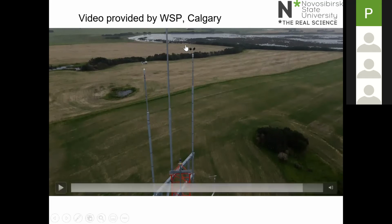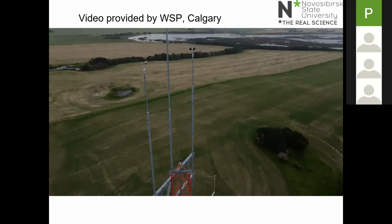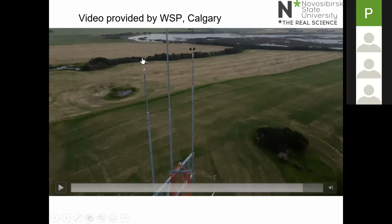These are very simple cup anemometers. You can probably imagine 3 cups that are on arms that are spun around by the wind. And the angular velocity of the cups is calibrated in a wind tunnel against the wind speed. And then it's put on an anemometer mast.